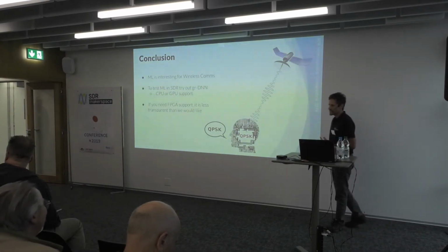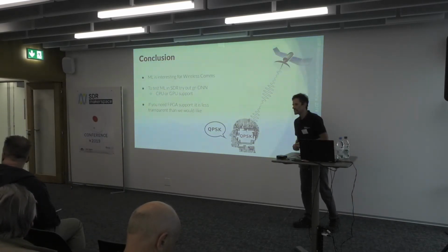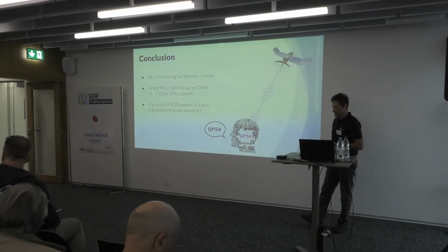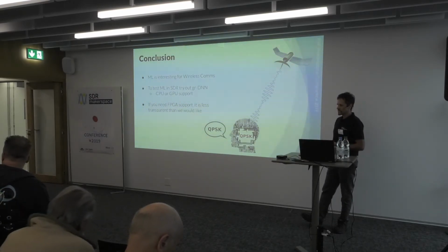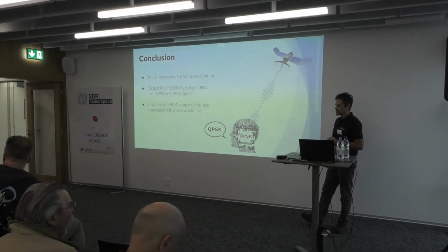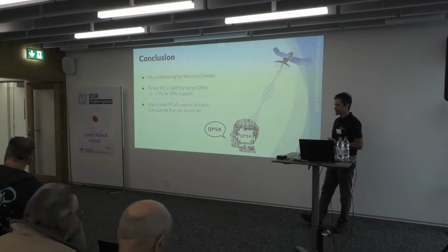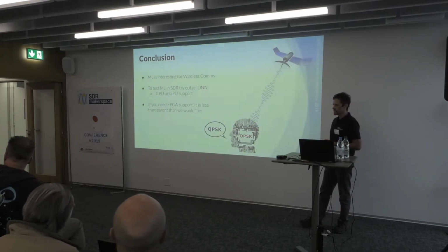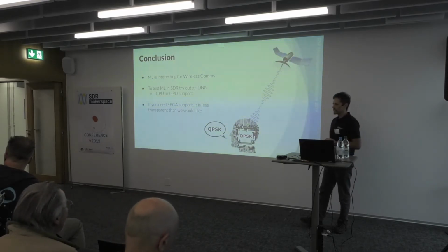I find it interesting when you try to find the modulation or the signaling format. I believe that this improvement that you have at a signal-to-noise ratio has to do with the fact that you're keeping the same signal format. In theory, if you try to work at capacity, as you increase the signal-to-noise ratio, then you also have to change the signaling format.